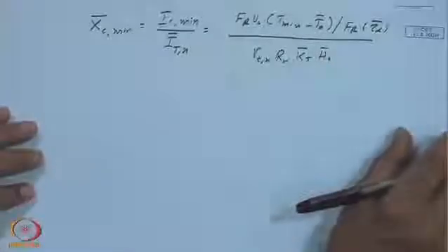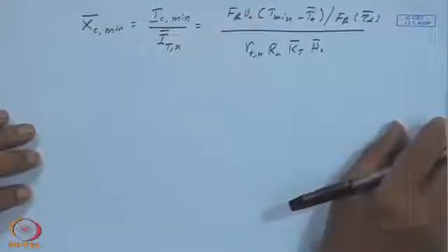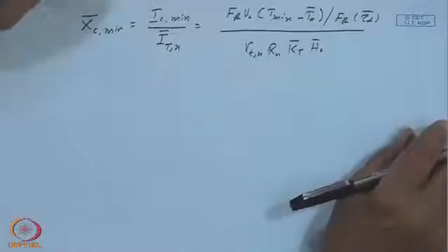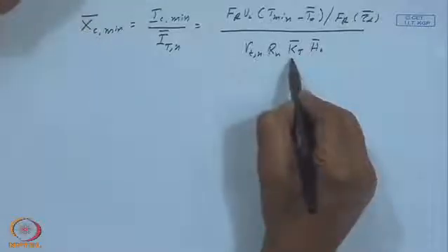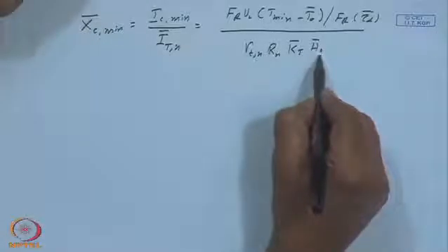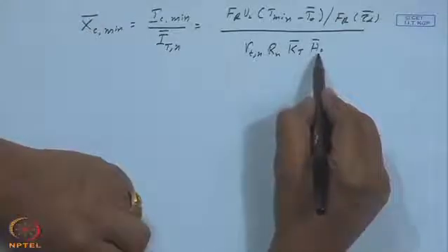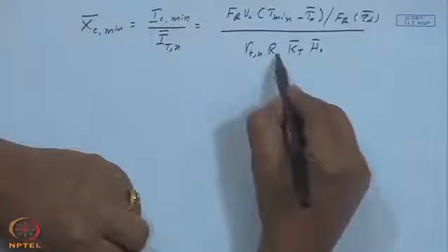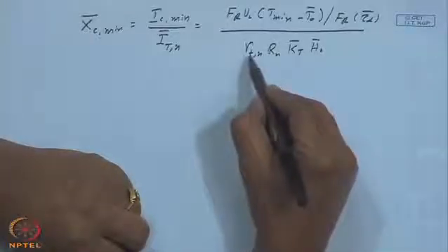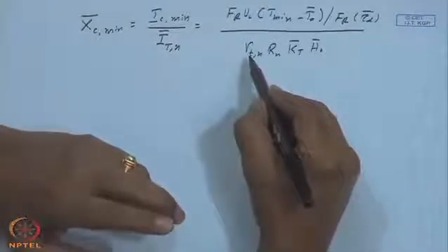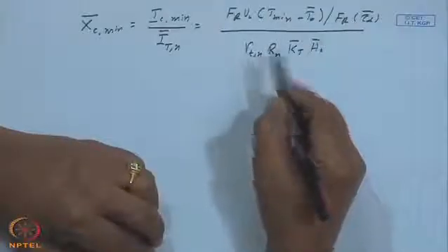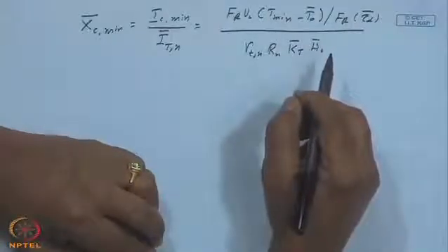I suppose you remember these symbols that we have discussed n number of times in the previous classes. And Kt bar is the monthly average clearness index, H0 bar is the monthly average daily extraterrestrial radiation, and R is the tilt factor, and RT is I by H, the Collares-Pereira-Rabl form of expressing the hourly radiation as a ratio with respect to the daily radiation H bar.